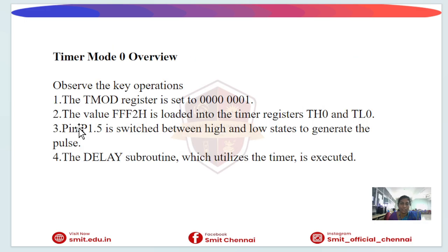Then the timer 0 overview: the timer is loaded with FFF2H into the timer registers TH0 and TL0. Thus, after the timer reaches overflow, TF0 becomes 1. This indicates that the required delay has elapsed.